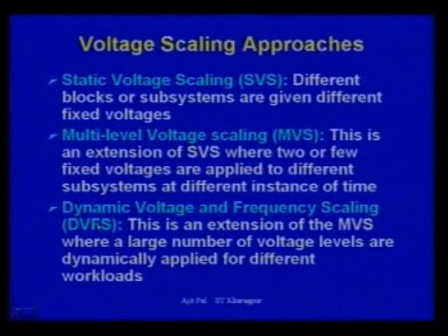Then finally you have dynamic voltage and frequency scaling. This is an extension of multi-voltage scaling, where a large number of voltage levels are dynamically applied for different workloads. Later on I shall discuss these techniques in detail.